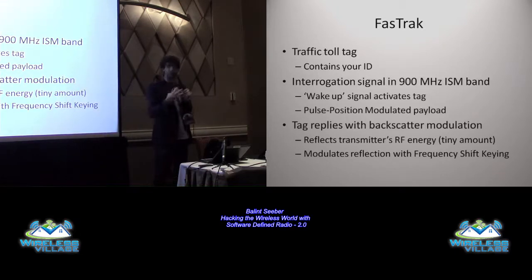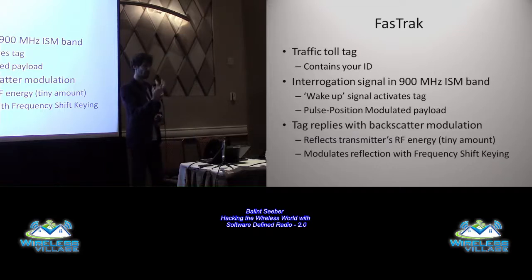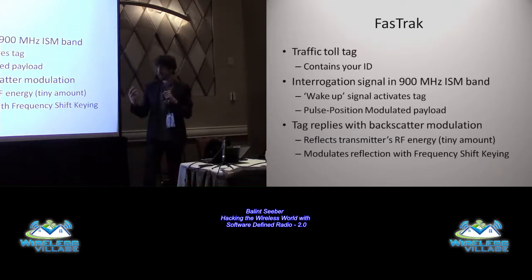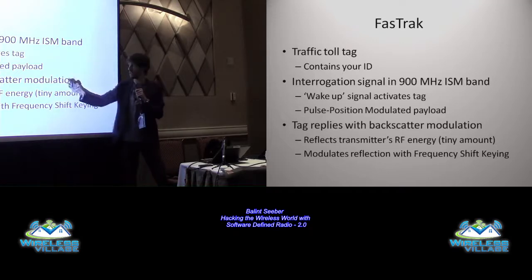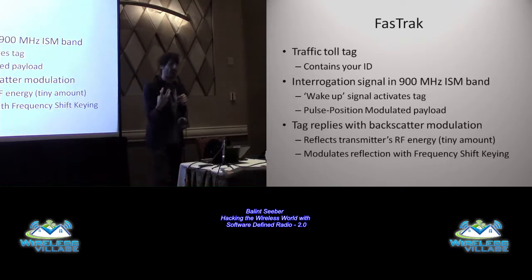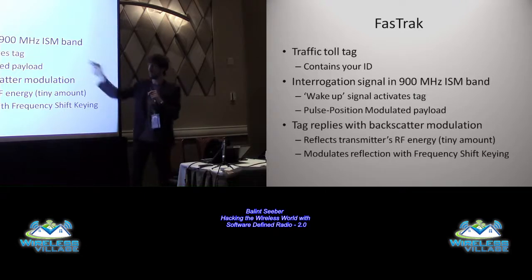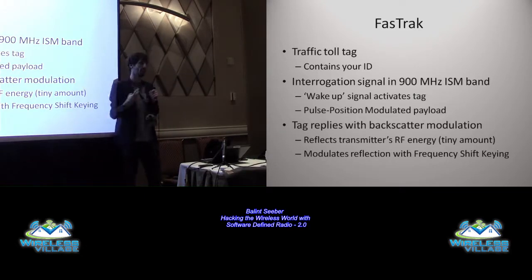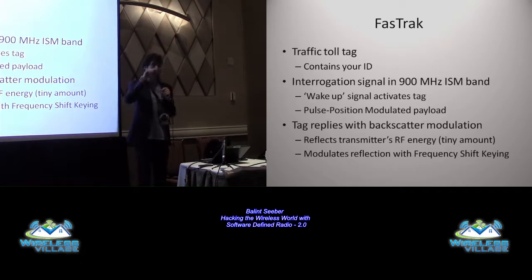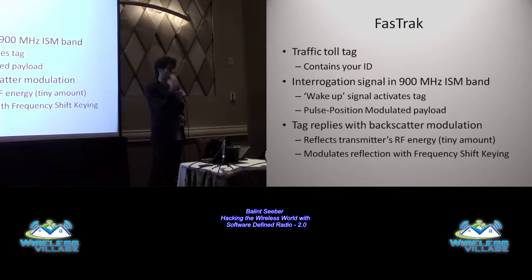And it uses backscatter modulation so that the receiver actually receives this backscatter energy. What's going on there is that your tag doesn't have an active transmitter in it. It's just a little long-life battery, but there's an antenna inside it, and it has a radio receiver. So when it's woken up and it receives this payload, it will actually change the impedance across the antenna in such a way that the receiver can see those very subtle changes in radio energy coming back, because the antenna will change its characteristics, change its radar cross-section, and the receiver can actually pick that up.